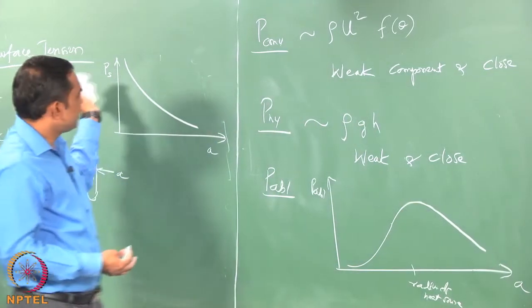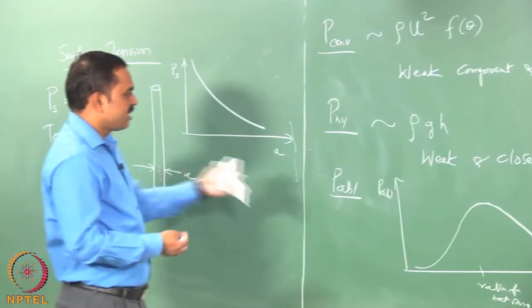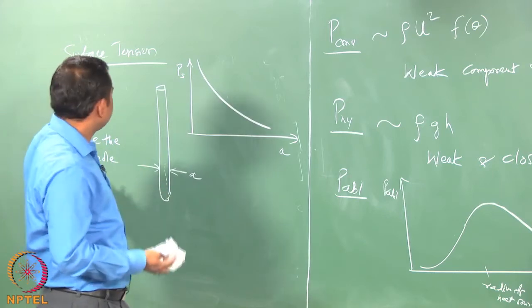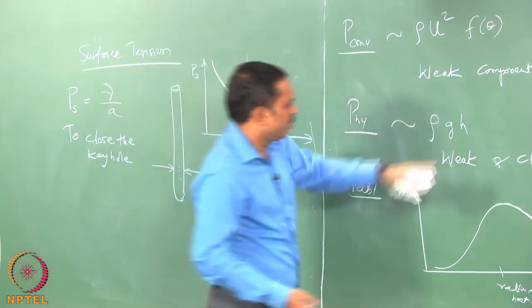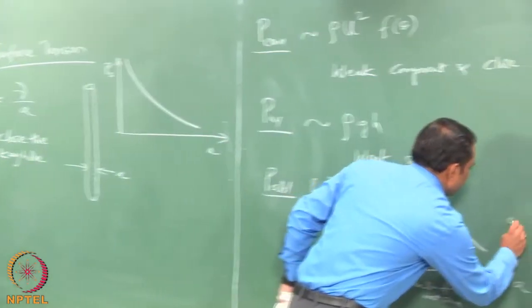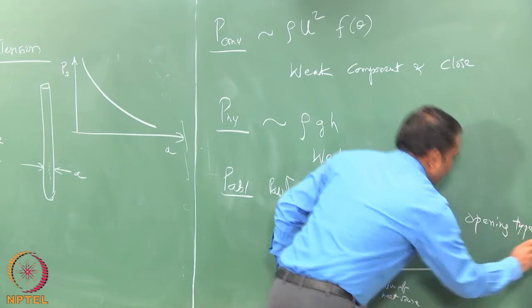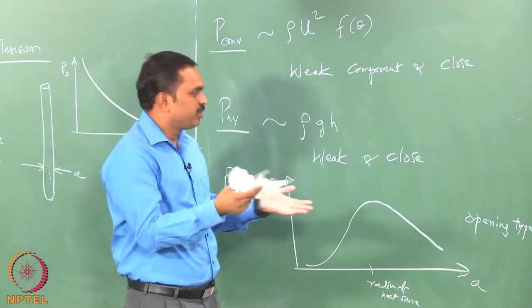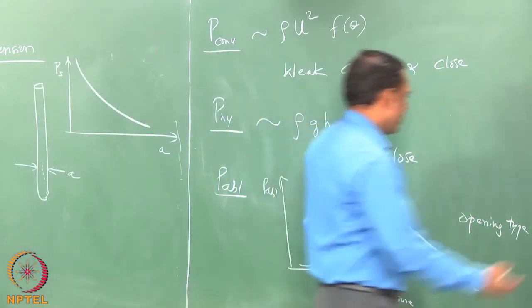So, if this is the variation of these 4 components, then what is the mechanism by which the stability of the keyhole is going to act? You can basically see which way is opening and which way is closing. So, the 3 factors are closing type, and this is opening type. Essentially we take a sum of the closing types and equate it to the opening type, and that should tell us about the stability. So, we would write that as an equation here as follows.